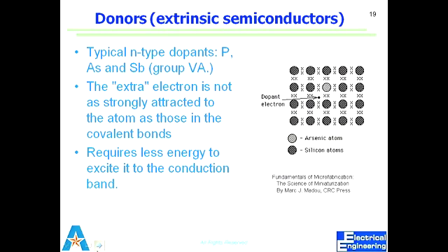So it sinks electrons essentially. P, phosphorus, antimony, and arsenic are group 5 elements. They have an extra electron used for N-type doping. So when it says requires less energy to excite it to the conduction band, it's in comparison to P-type materials, where the holes are considered more bulky and they require more energy, bulky in terms of their mass.